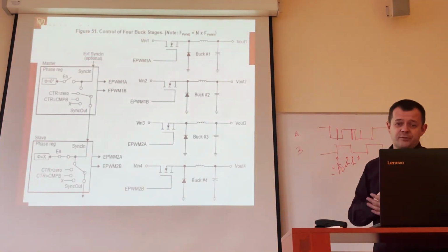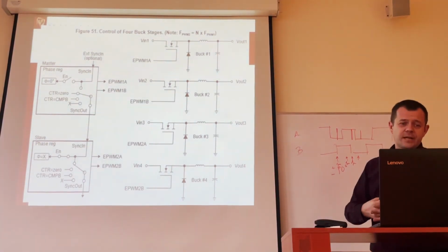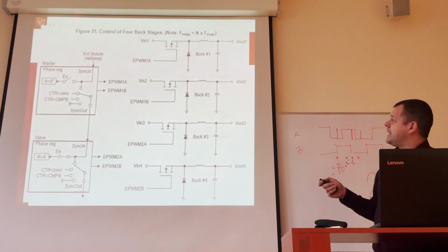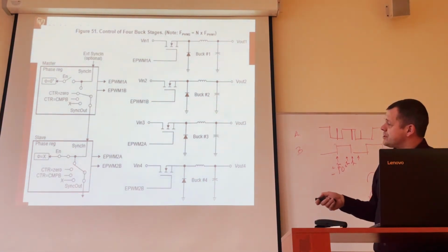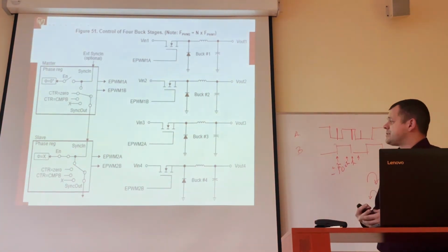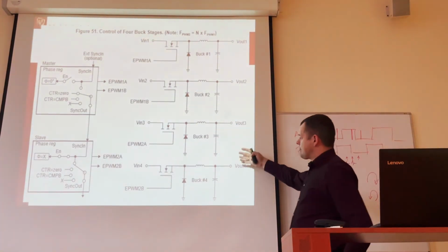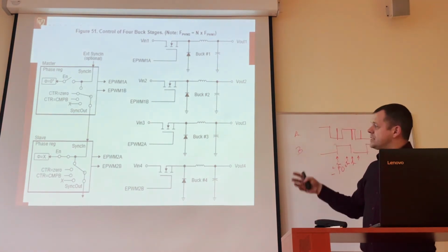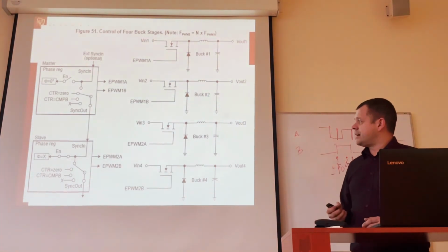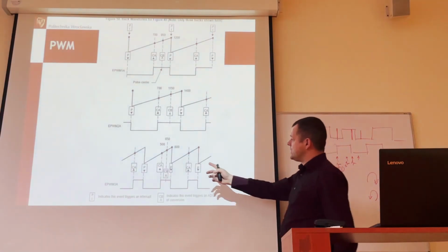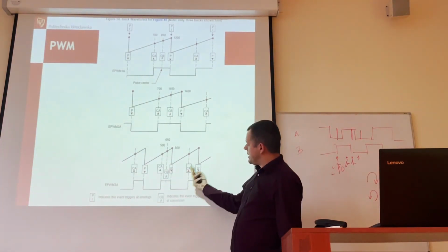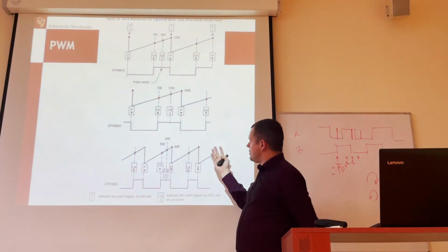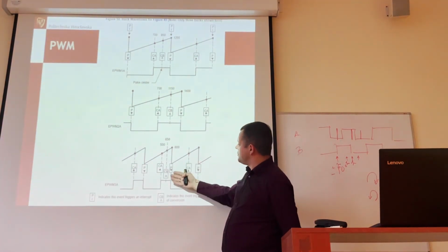To avoid this, we can synchronize. We can synchronize everything, it is possible. We can switch on the synchronization here, and we can synchronize the converters, for example, the power switching between the timers. And thanks to this, it would be possible to avoid the problem: if we want to make the ADC conversion, in this example it's not possible to convert anything because we never know when the switching will occur.